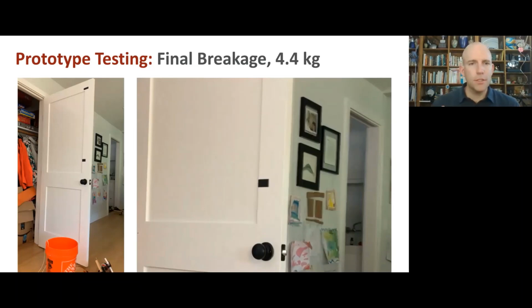So if I were to try to do this better, to make it pull up a heavier load, I would redesign the system to have a smaller vertical separation between the wheels, so I could do a little bit better leverage that way instead of making the payload lever longer. And I would have tried more permutations on the contact between the drive wheel and the wall. So perhaps a thicker rubber, different kind of rubber, or maybe even no rubber, and we might get a more linear relationship between the normal force and the static slipping force.